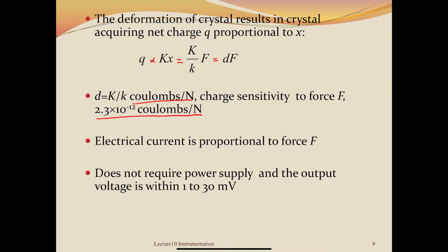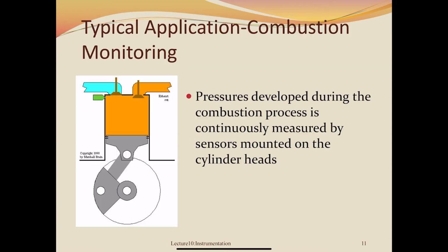By looking at this equation, we can say that the electrical current is proportional to the force applied onto the crystal. Piezoelectric sensor is a passive transducer where it does not require power supply and the output is very small, which is only within 1 to 30 millivolts.